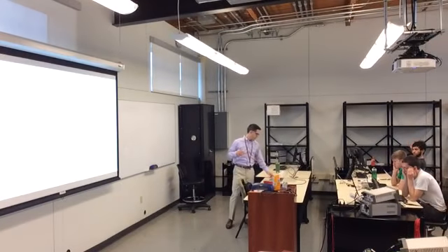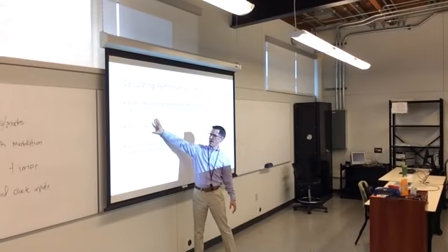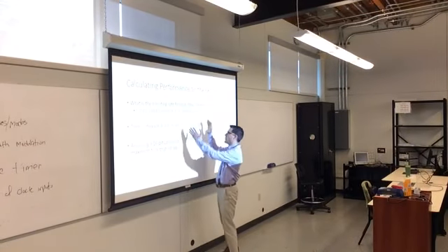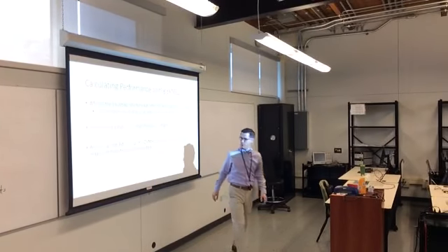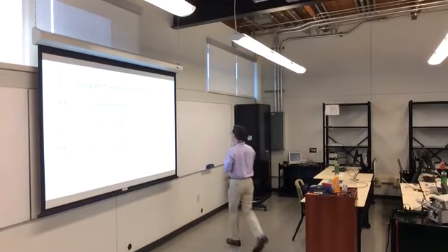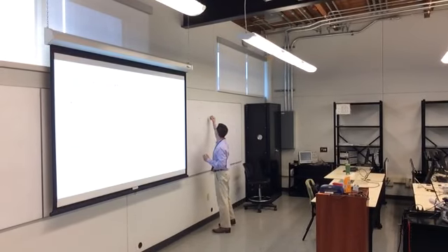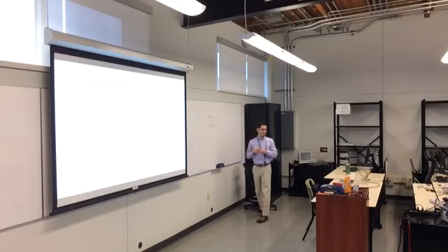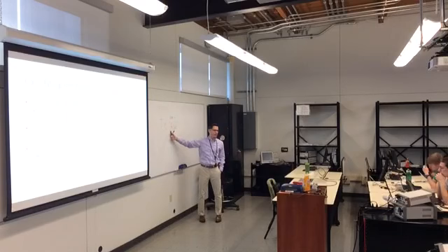So your time is actually the maximum value plus 1 divided by the clock frequency and then divided by that prescale value. So if you were going to write out the time, t is equal to max plus 1 divided by frequency, divided by your prescale. If you don't scale your clock, you're just dividing by its frequency.